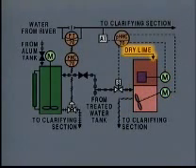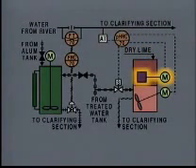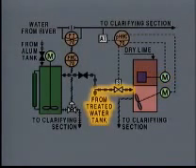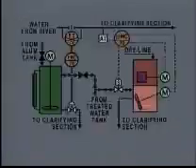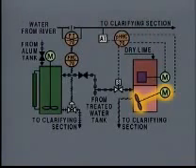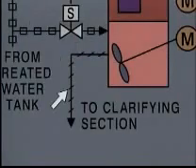Lime is added to the hopper manually. The shaker dispenses the lime from the hopper into the mix tank. Treated water enters the system through this piping and is fed to the mix tank. The line symbol indicates that the treated water line is made of copper. The mixer mixes the lime and water. The mixture then flows out of the mix tank. The line symbol indicates that the mixture flows through a rubber hose.